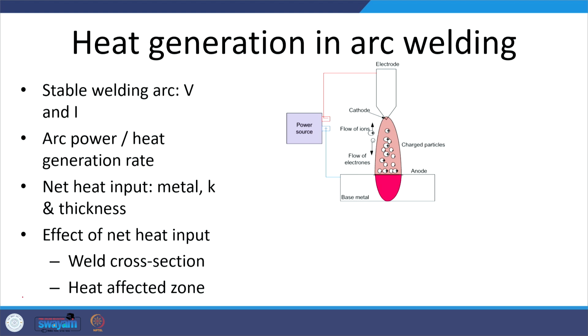But if the heat being generated, like say 200 is the current and 20 is the arc voltage and the welding speed is say 10 mm per second, then we will be getting like say 400 joule per mm, okay. So, if this is too much, then if this is one way, another way is that we can also divide it by 1000. What is the meaning of that?